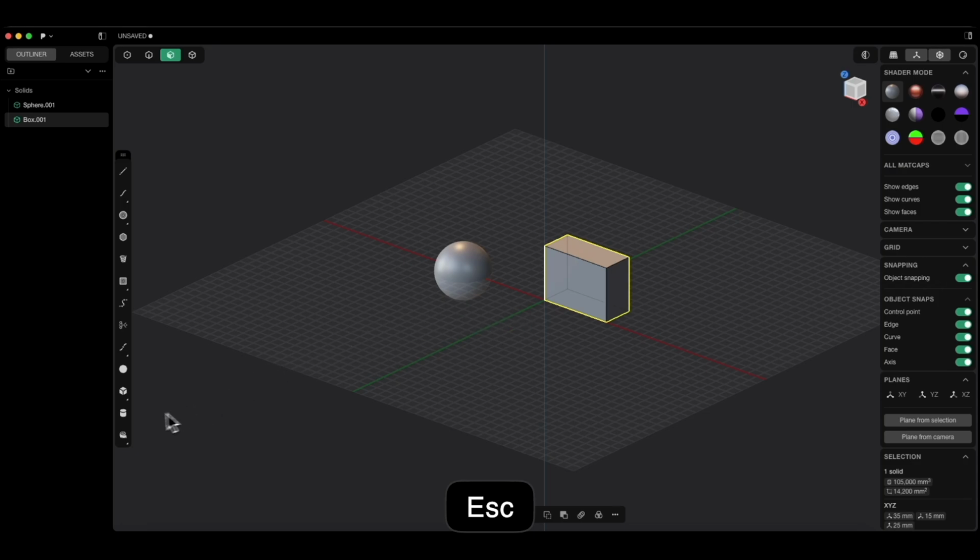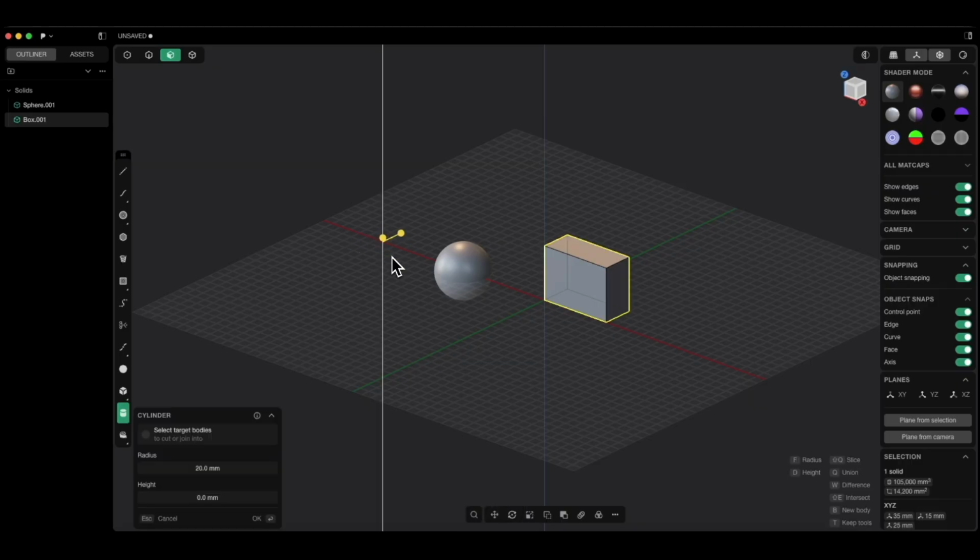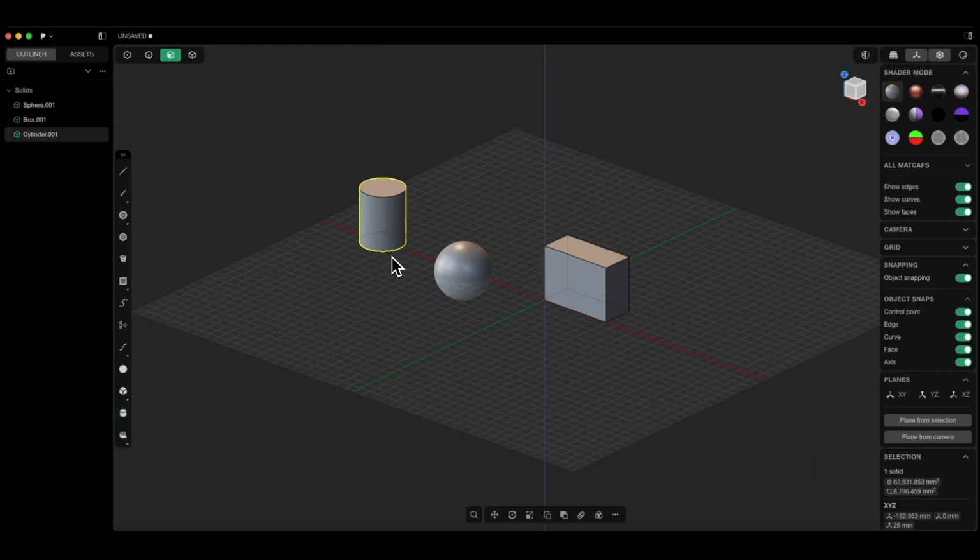We also have a command for creating a cylinder. We specify the center of the cylinder, press the Tab key, enter the diameter and then enter the height of the cylinder. So as you can see, we can also create these basic shapes, and using these shapes I will quickly show you how Boolean operation works, that is, how we can subtract one solid from another.